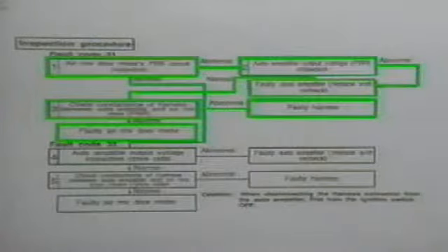Troubleshooting procedures for the mix and mode actuator circuits are very similar. The charts are divided into 2 areas: potentio balance resistor, or PBR circuits, and motor drive circuits. Fault codes will lead to the correct starting point of the chart. Because of the similarities between the 2 actuators, only the mixed door chart will be discussed.